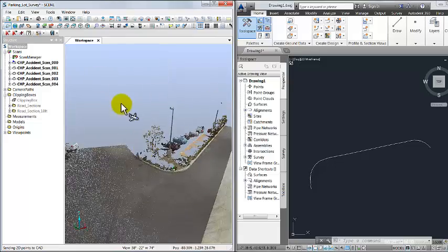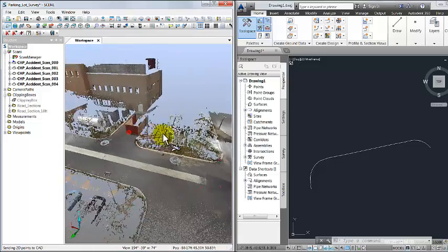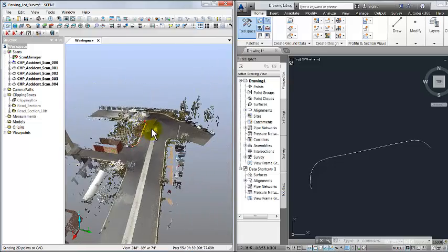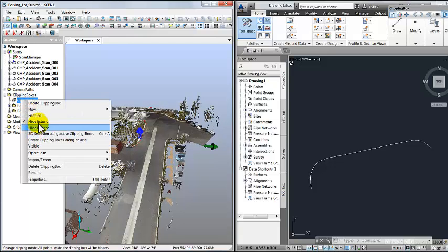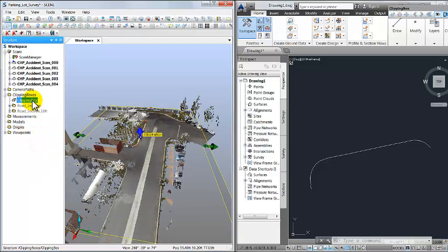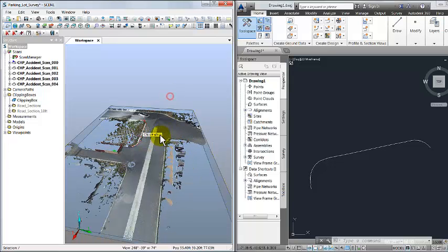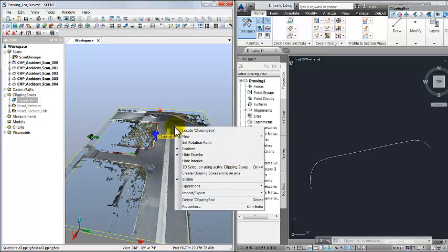and then do some of the other things like our surfaces sort of as a separate piece. So one thing we may want to do here, and what I would recommend doing before transferring this, is doing some clipping. So again, create a clipping box, as in this case we have already done, and go ahead and activate the one that I'm using, but get rid of basically all the data except for what's pretty close to the ground and things that are at the extents of your data or of the surface that you're interested in. Right click inside the box, do a 3D selection from your active clipping boxes, and then again, once that is finished, export those points as E57, PTS, or XYZ.